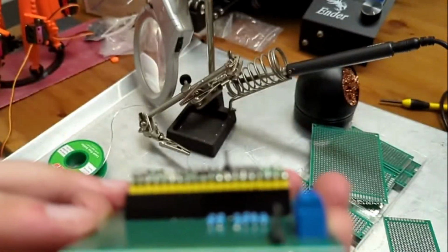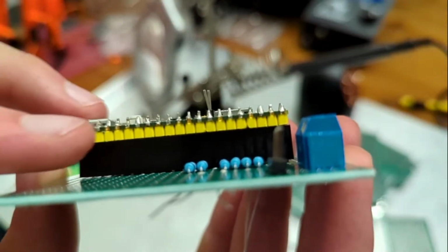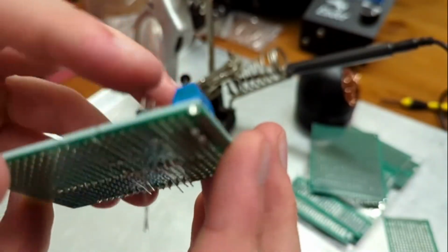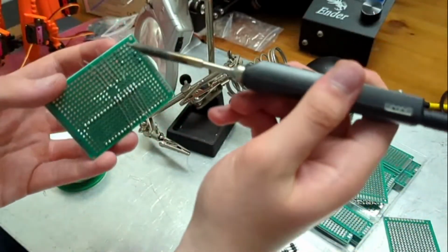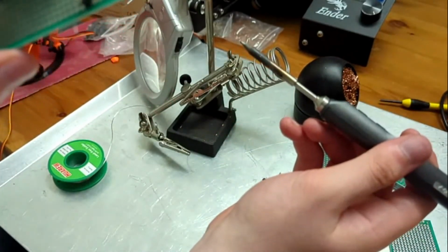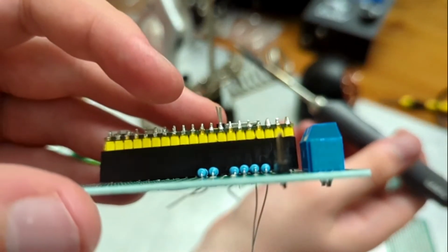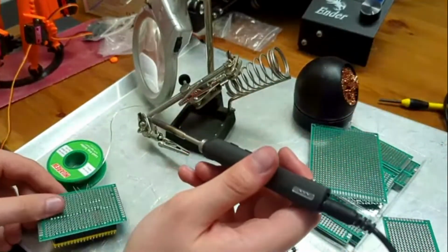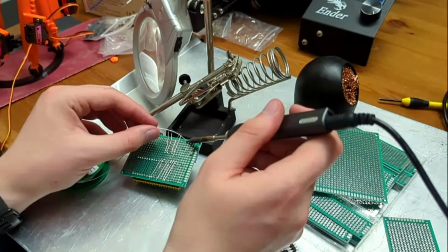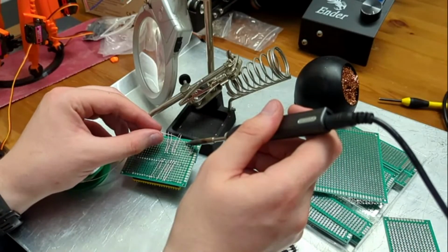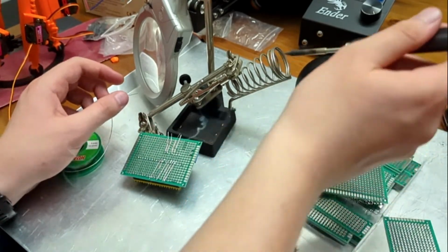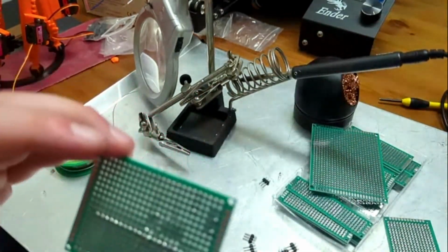And you see how it's a little bit crooked? See if we can focus. This pin header I just soldered is crooked. What I can do is I can loosen that one solder joint and hold it in place while it cools again. Since I only did the one, it's super easy to unsolder and resolder. And now it's sitting a lot straighter, which is a lot nicer to work with. And that solder joint holds it in place while I do the rest of the solder. There we go. Look at that, super duper easy.